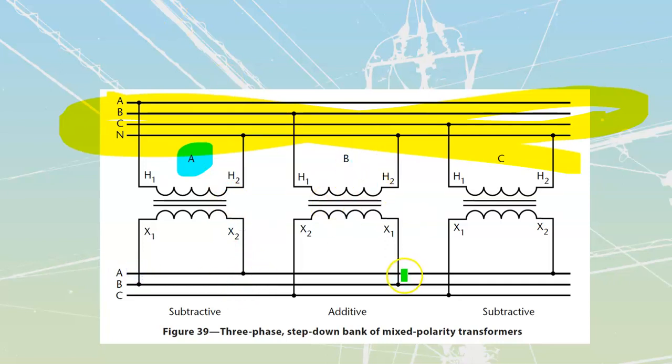If I take a look at B, my BX1 goes over there and connects across to C. My CX1 connects to its line, connects back to A. That's all good to go. But the very first transformer over here is screwed up. Let's reconnect that transformer. It should have X1 to A, and it should have its X2 going down to B over there.